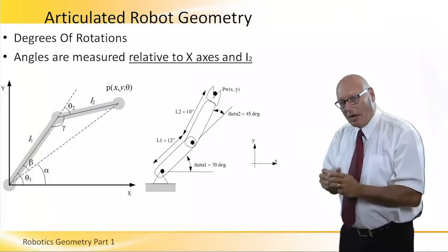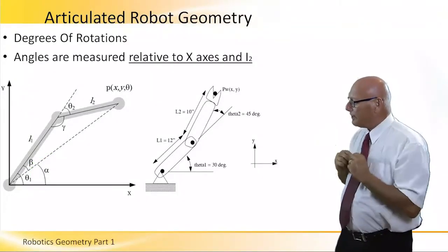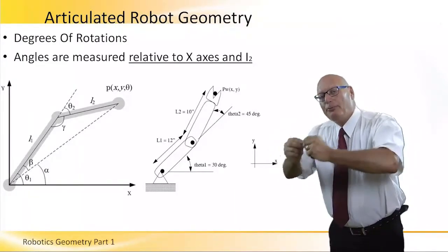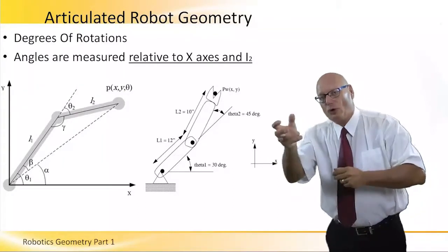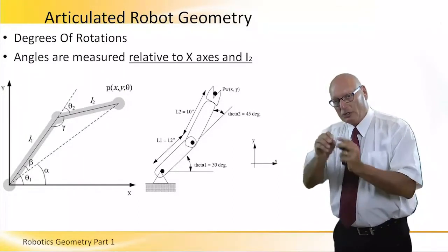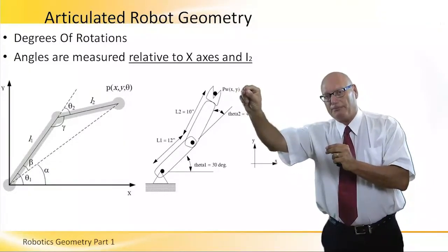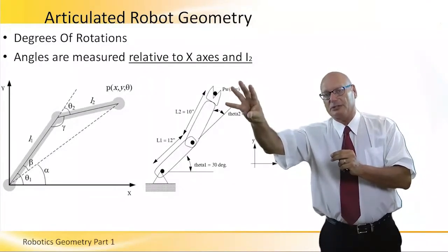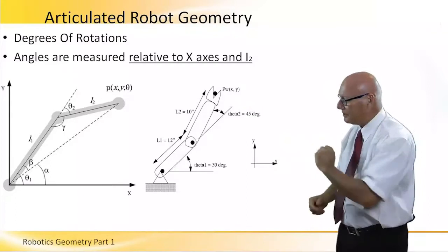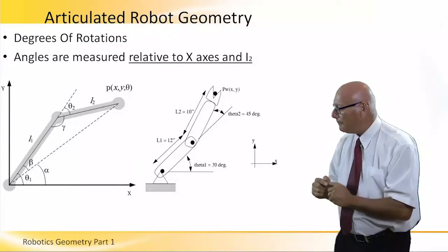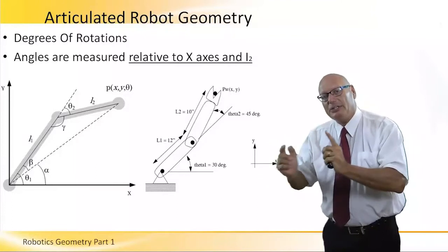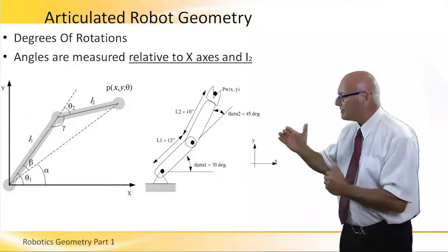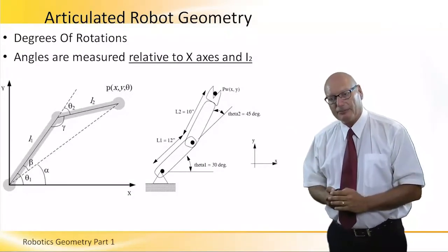All these angles are in order to help us define the position of the gripper prior to beginning the roll, the pitch, or the yaw. So we have to move the robot to a particular point where the gripper will be. When we get there, the operation will start. But in order to get there, I have to find alpha. In order to find alpha, I have to move the links and the joints of the robot in order to create beta. And alpha plus beta equals theta 1.